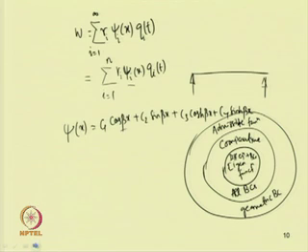So, let us now discuss some of the boundary conditions in the transverse vibration of the beam. For example, in case of this simply supported beam, at x equal to 0 and x equal to L, the boundary conditions are both displacement and slope equal to 0. Both displacement and slope equal to 0 here.